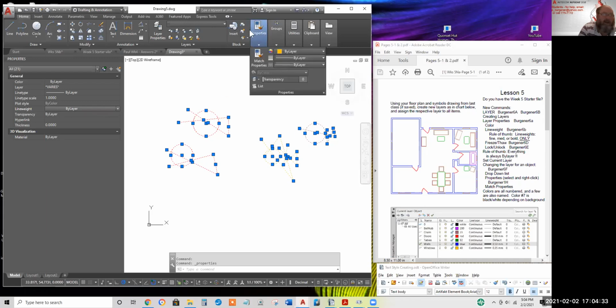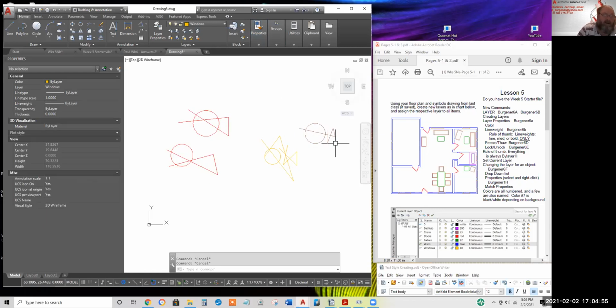I wish there was a way I could put a piece of masking tape across this panel of your computer, or somehow nullify it this early in your training so students won't get in the habit of assigning color independent of layer. I'll hit escape to bail out.